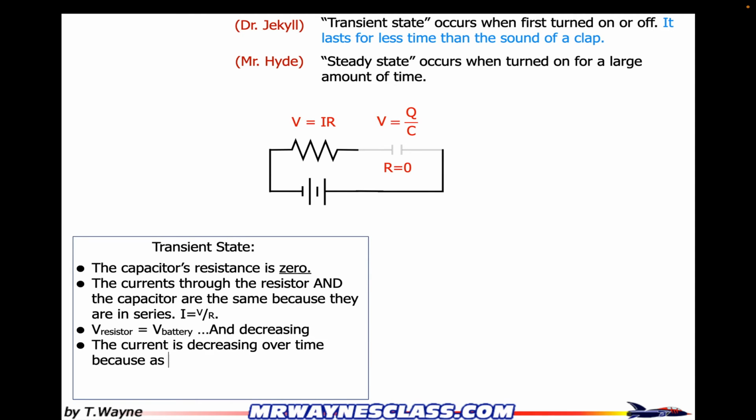At this point, the current is also beginning to decrease over time as the capacitor fills up and the flow begins to slow down. As charges pile onto the plate, the charges that are on the plate already are repelling charges from coming onto the plate. And so it becomes harder and harder to add charges to the plate. So in this transition period, there's beginning to be some kind of resistance. That's just giving you the fill-in of what's happening in between, but all I really care about is what happens when I first turn on that switch, in that moment of contact.